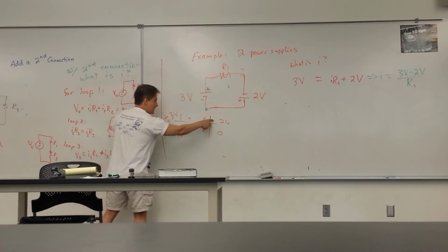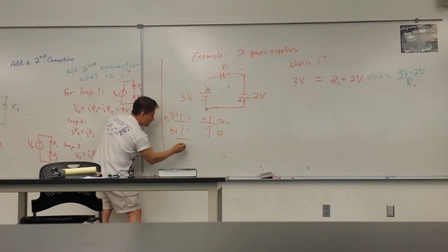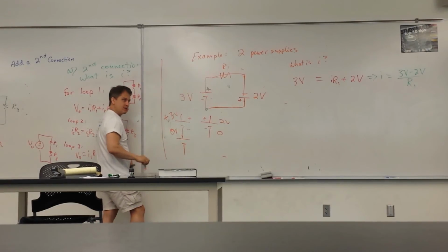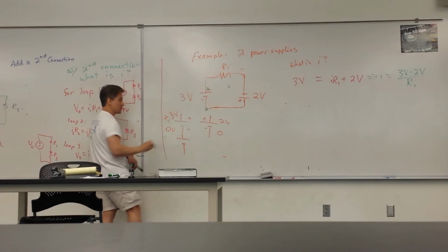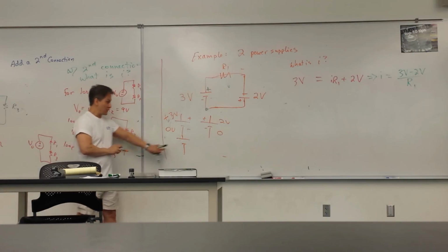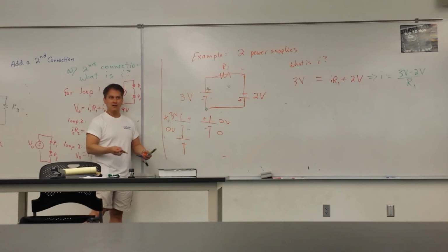So if I plug this into here, it doesn't violate any rule. By plugging that in here, all I do is establish that if for some reason we could say with absolute certainty this is 0, then this is -2. It's just 2 volts below. But it doesn't matter. We never talk about the absolutes, and that's why at some point you just start calling things V, because it never really matters what 0 is. It's just the voltage across something.